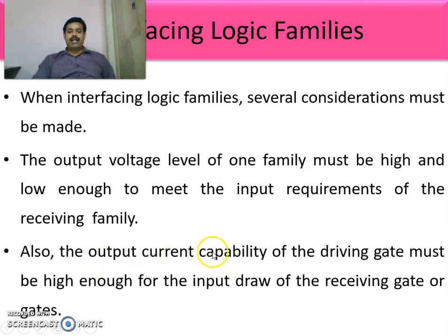Also, the output current capability of the driving gate must be high enough for the input draw of the receiving gate or gates, if we are connecting more than one gate. So the main thing is, while connecting the output of one family to the input of another family, the output voltage level and the output current level must satisfy the requirements.